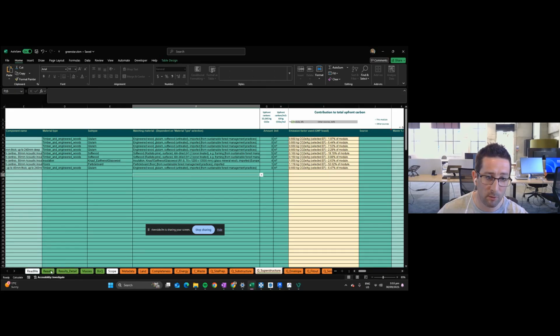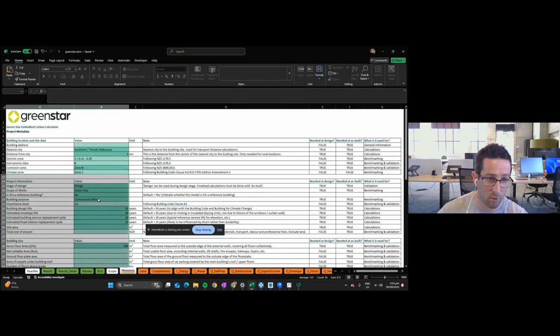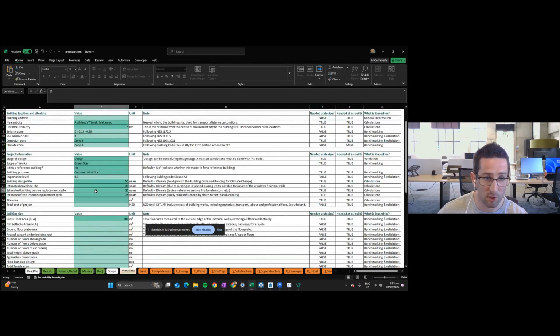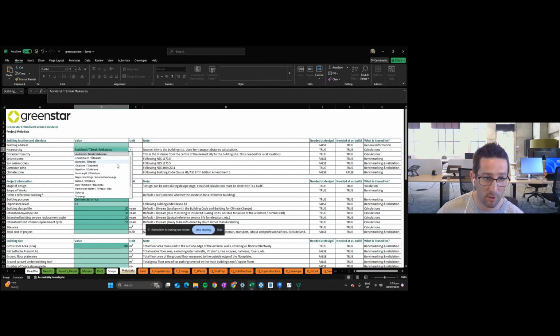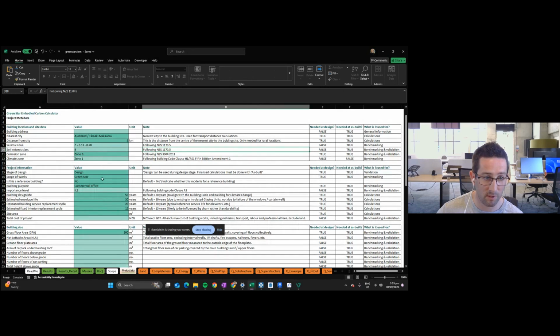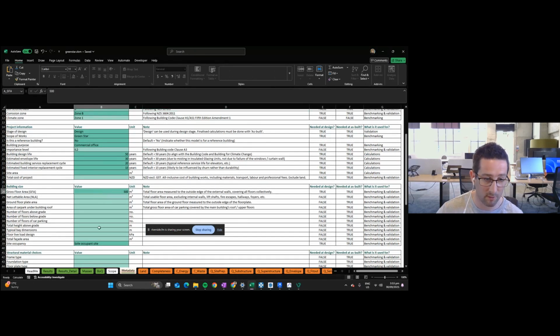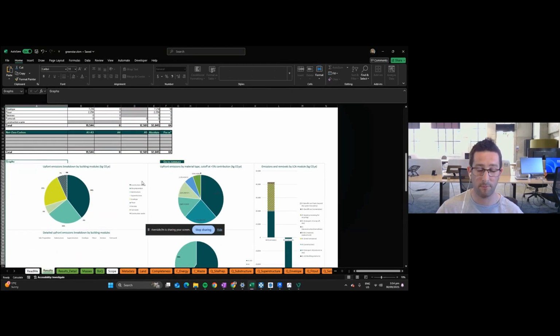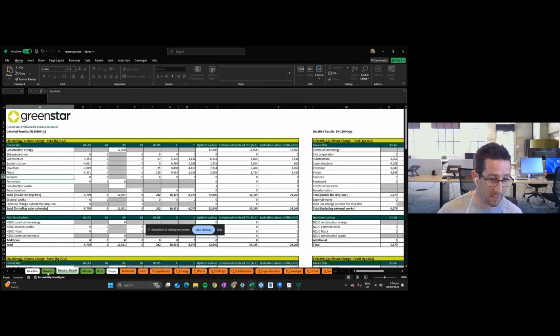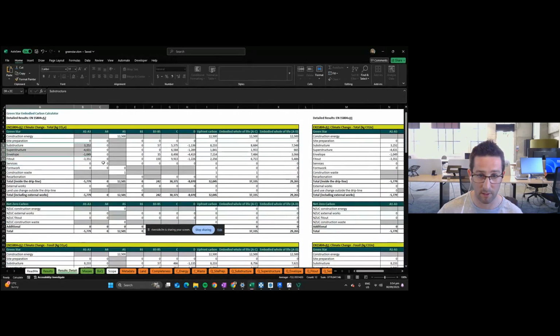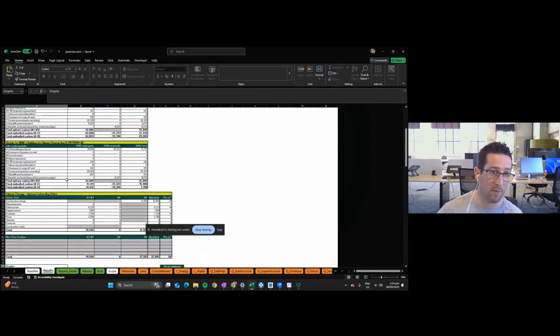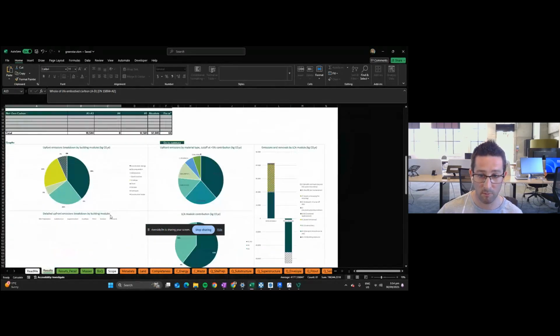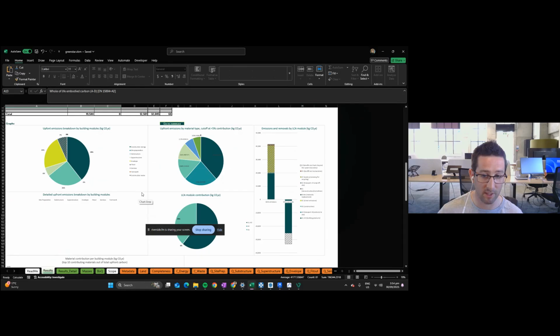And all you need to do now is make sure you're putting information about your project in, which is just what city centre it is close to, how far away is your site from the city, and GFA, a few other small details, and you'll be able to explore the full life cycle. So not just that A1 to A3, the full life cycle through to end of life of those materials. There's really good results tabs within this tool where we can explore in a high level of detail, more macro level of detail here, or, personal favorite, the graphical results that we see here.